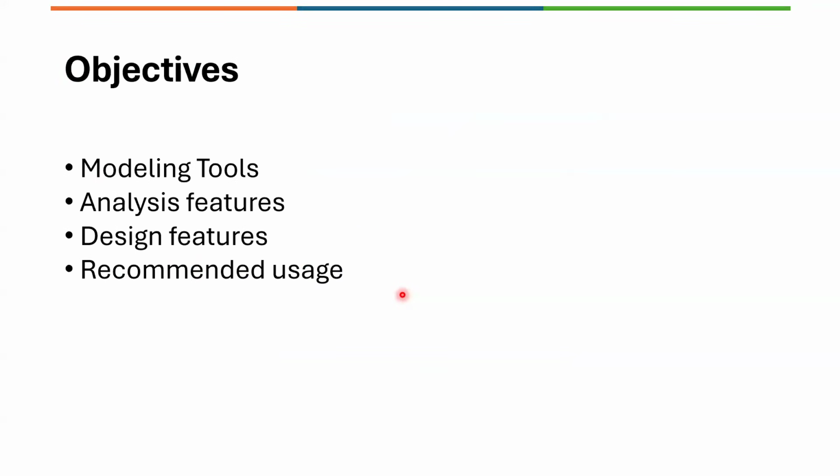So today's objectives are introducing you to the modeling tools available within the program, the analysis and design features, and recommended usage of the program. So this will be focused on the floor slab system. In the previous webinar on SAFE, we discussed the foundation system that is already available in our YouTube channel.